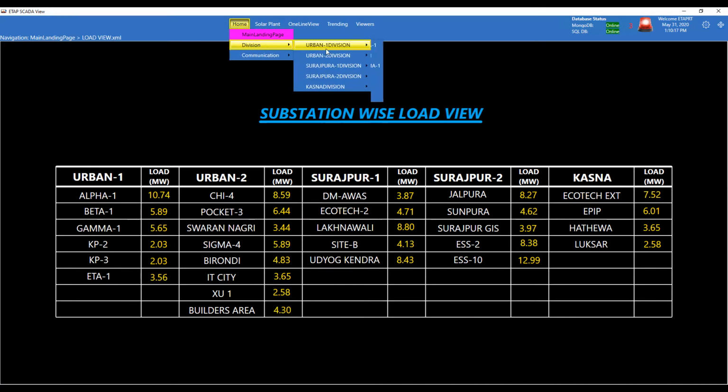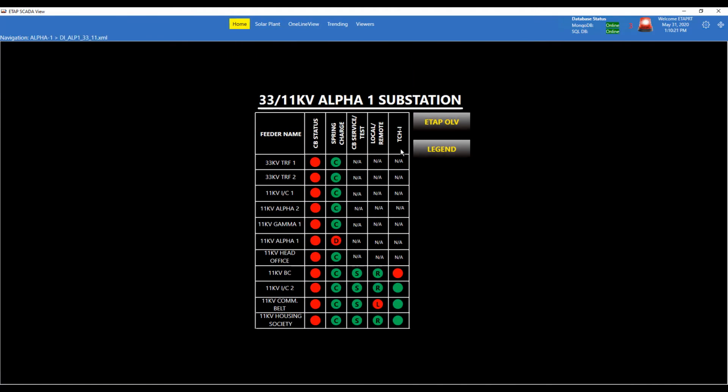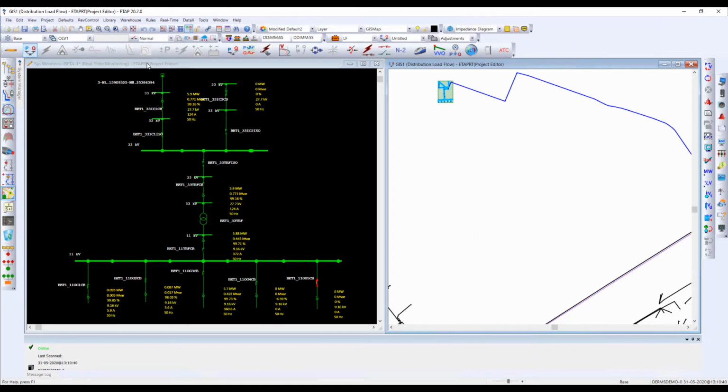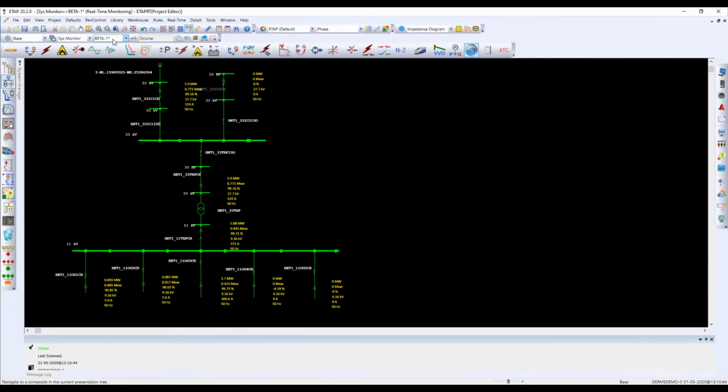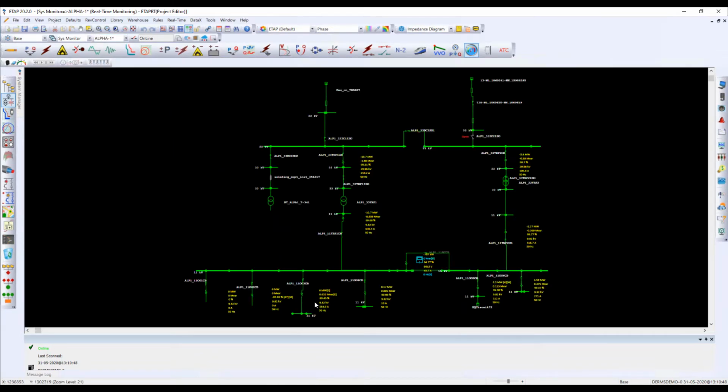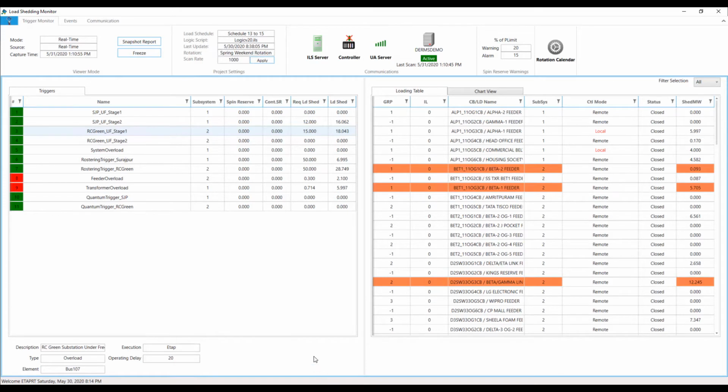The real-time system is constantly monitoring the operating conditions throughout the system, such as loading levels, frequencies, currents, voltages, power factors, and is aware of the current topology of the network along with any temporary interconnections such as jumper or a cut. All these electrical signals measured from the field along with any non-electrical real-time data such as key energy market parameters, weather data, set points requests or recommendations from the RTO or ISO, as well as any maintenance, repair, or breakdown activities being performed on site, are brought into the ETAP real-time system and used by the distribution load sharing engine for making intelligent decisions.